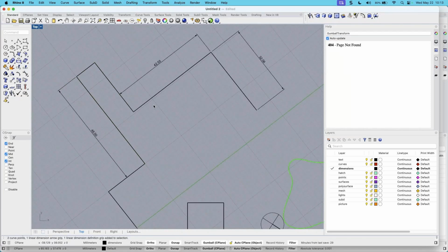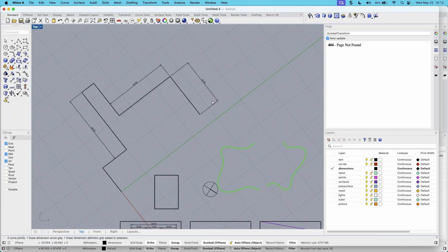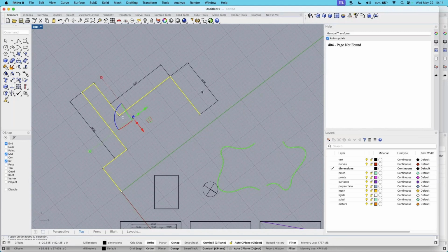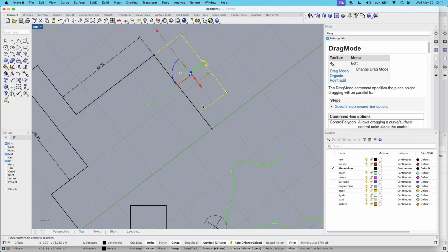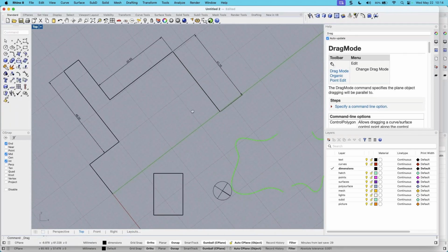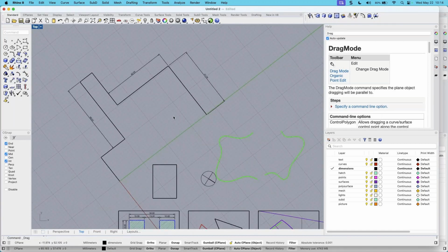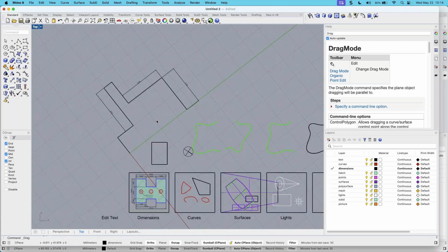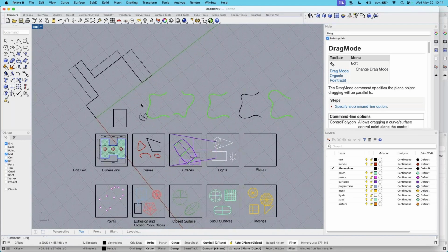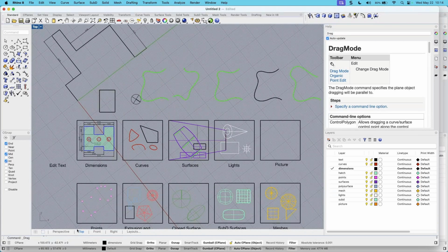Anyway, what I wanted to show you is that this distance here is determined by this endpoint, and if you move that endpoint, then you're changing the length. When I joined this together as a polyline, the history ran away on the dimensions, and I got a warning for that. If you look back on the video, it said that. If I didn't do the exploding and joining to show you that, these dimensions would have been historical. Okay, Eva, does that answer your question?